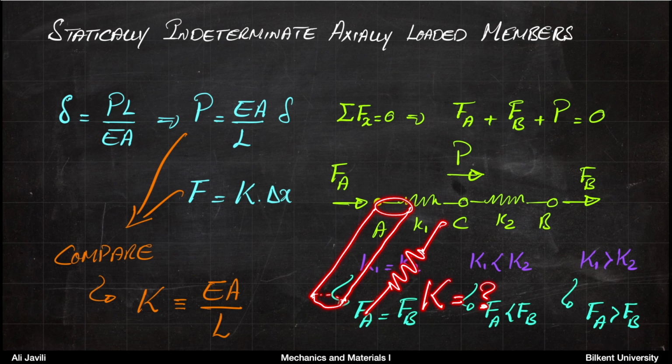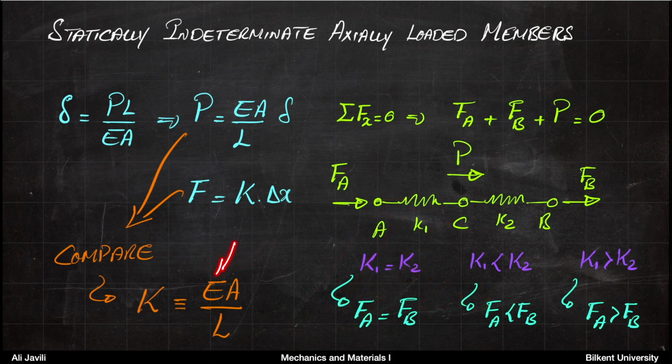You can imagine if you increase the cross-sectional area or if you increase the stiffness, the effective stiffness of the truss member should also increase. So Young's modulus and cross-sectional area make sense to be increasing stiffness when they increase, but also you can imagine if you increase the length of a member, it gets less stiff, it gets more compliant.